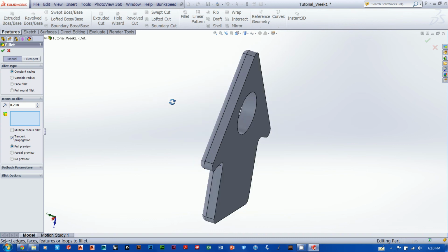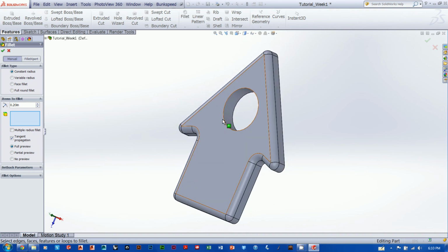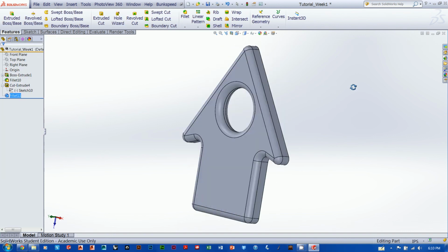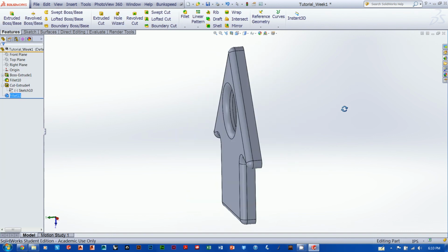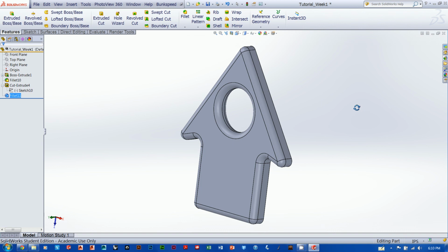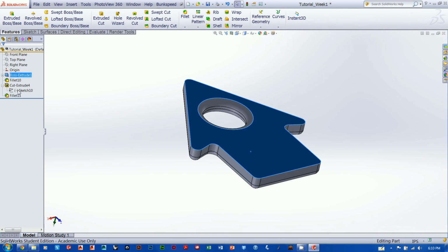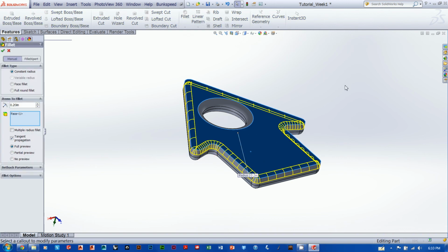We have a lot of different options. Or if we wanted to add a fillet to both sides, we could just select this whole face of the cut extrude and add a fillet on the perimeter of this actual face. So let's just click that, and we'll see it's going to go ahead and do that like a nice machine. So now it's added the fillet to both sides. And since we did that, we'll just go ahead and add another fillet to this side too. Oh, come on. There we go.